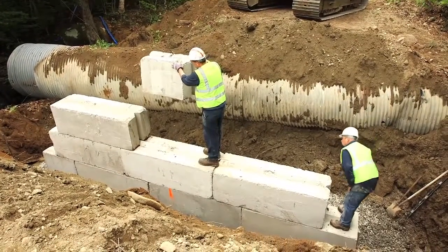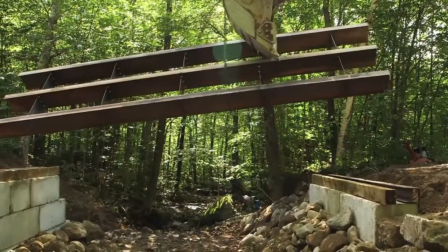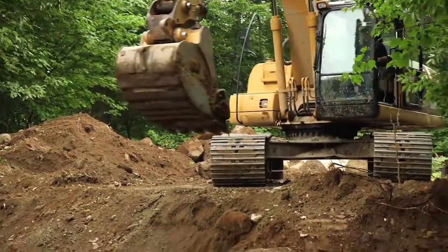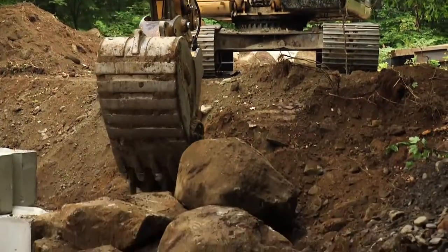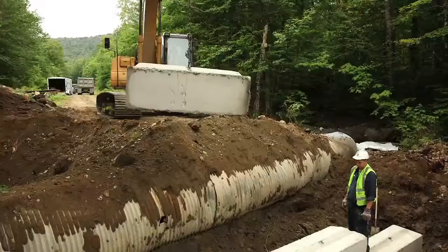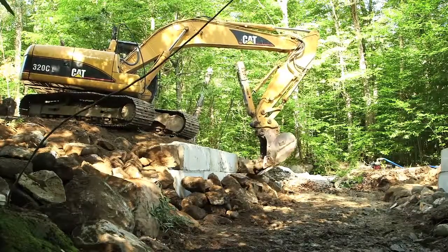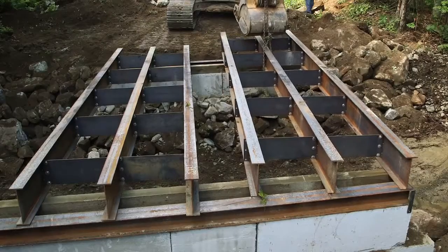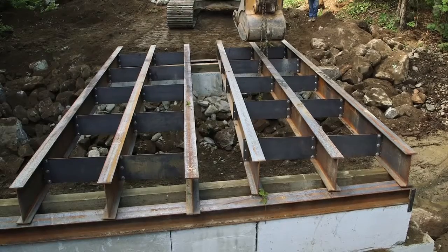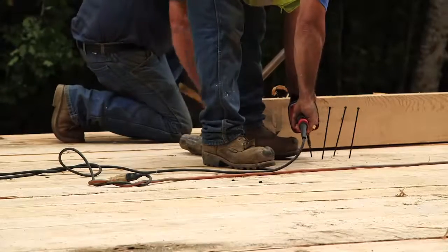This type of construction consists of non-reinforced concrete block abutments, steel or timber girders, and timber deck bridge. Typically, this construction can be done with a medium-sized to large excavator. Installation involves site preparation, excavation, and placement of the abutments, girders, and rock stabilization with an excavator. The steel girder assembly can be partially prefabricated prior to delivery to the site to minimize any on-site fabrication. The installation of the timber deck consists of basic carpentry work.